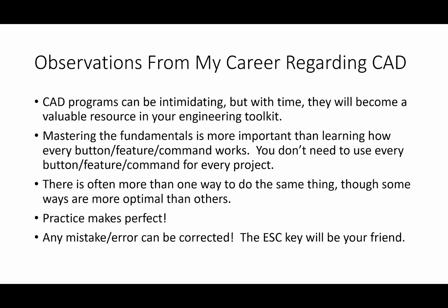One of the most magical buttons that we're going to use this semester is the escape key. Sometimes when you're using CAD and you get into that zone, you don't know whether you're just navigating CAD or you're inside a command. Just hit the escape key a few times and it'll get you out of your command. The escape key is your friend. That's more of an AutoCAD piece of advice than strictly Inventor, but I mention it to close the loop that any mistake or error can be fixed. I don't want you to be scared of CAD.